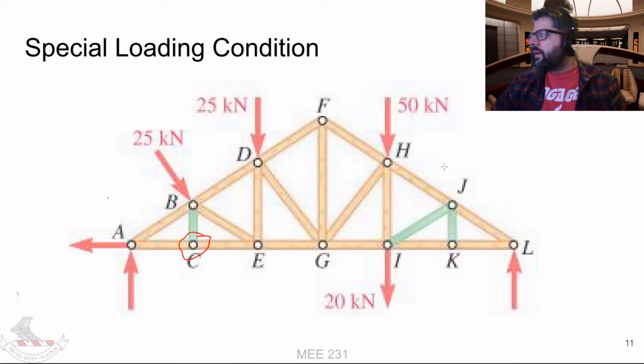And then next up on this side here, so we got the joint at K, same deal as C. So we know that this member here, JK, it's got 0 force there too. And then once we apply that, we're saying that JK isn't holding any load. So we can basically redraw the joint at J in terms of HJ, JL, and IJ only.